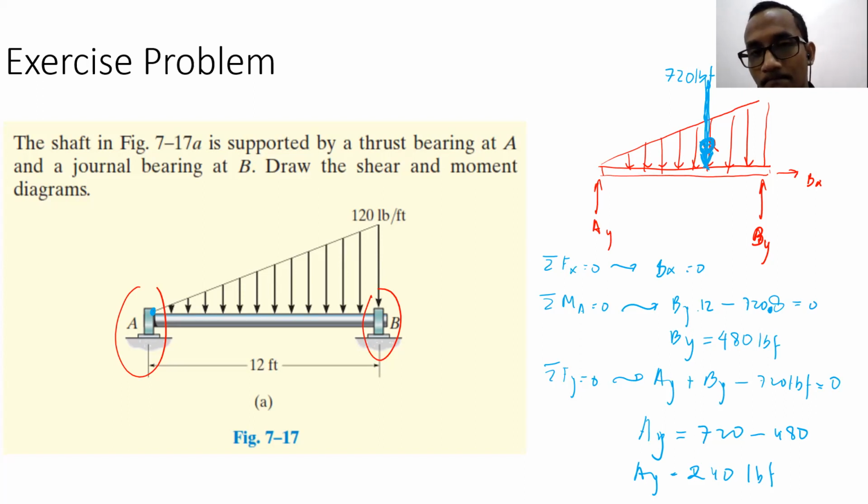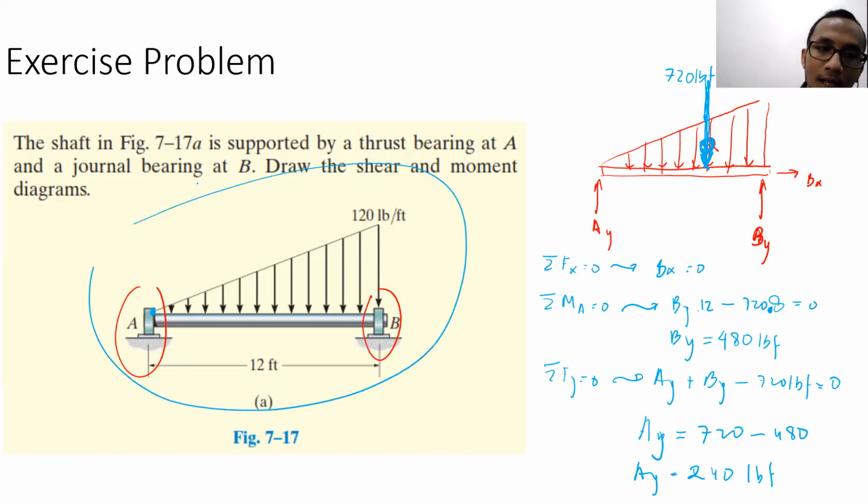Remember that whenever we do the cut, we don't consider the representative concentrated force. We draw the representative concentrated force only after we finish the free body diagram. So where are we supposed to carry that? There is no representative concentrated force there.